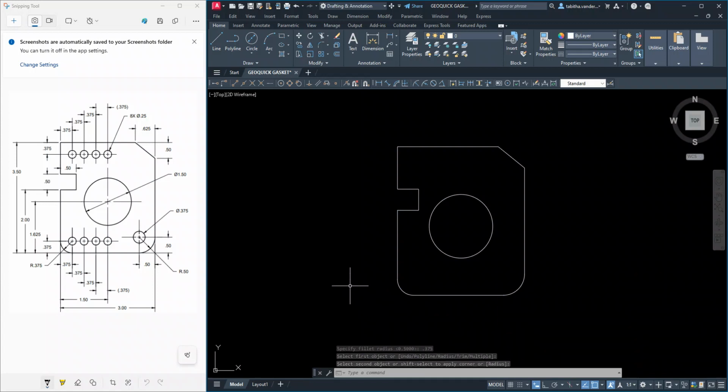Okay, next, we're going to get these circles here, and we don't have to individually place each of these circles. We could if we wanted to, but in this exercise, we're going to review the array command. So all we need to do is get one of these circles, and then we'll do the array command to copy that circle over this way 4 times, and then that row up 1 time up here.